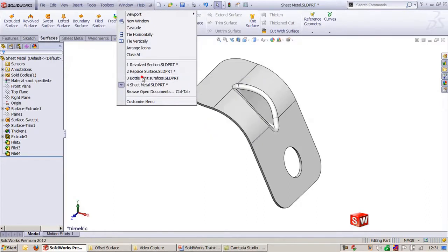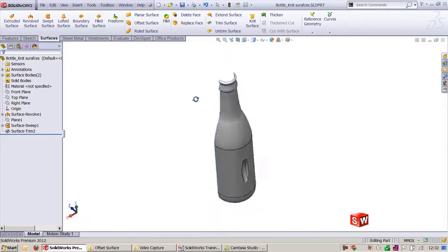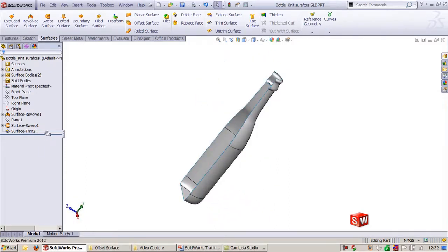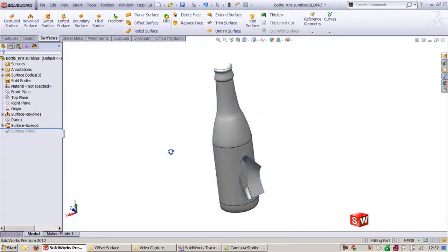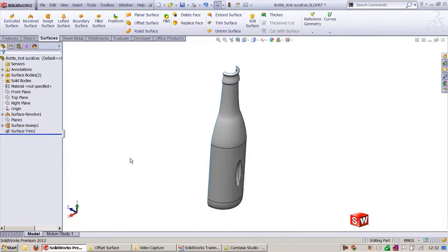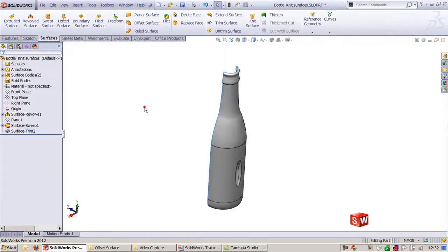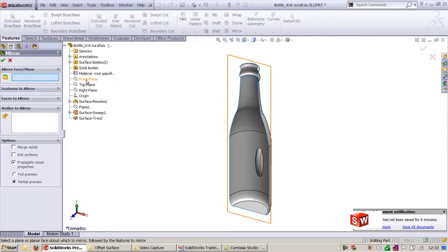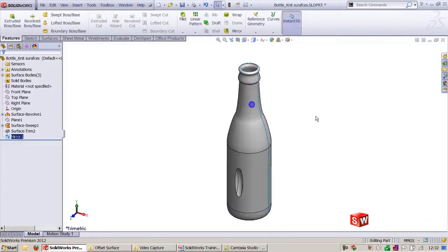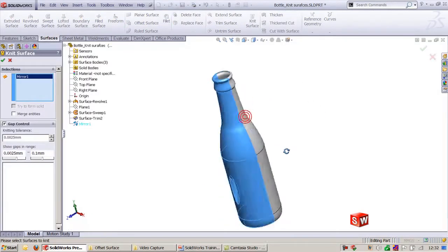Here we will see joining the faces and giving thickness. This is the sheet, and it is created in this way. First, start with the revolve, and next we created a sweep feature here, and using trim we trimmed this. You can see here we are using mutual trim, two surfaces selected and removing this unwanted portion. Once we complete it, we mirror this feature based on the front plane, mirroring this body. These are two different bodies. Use knit and say these two should be united,